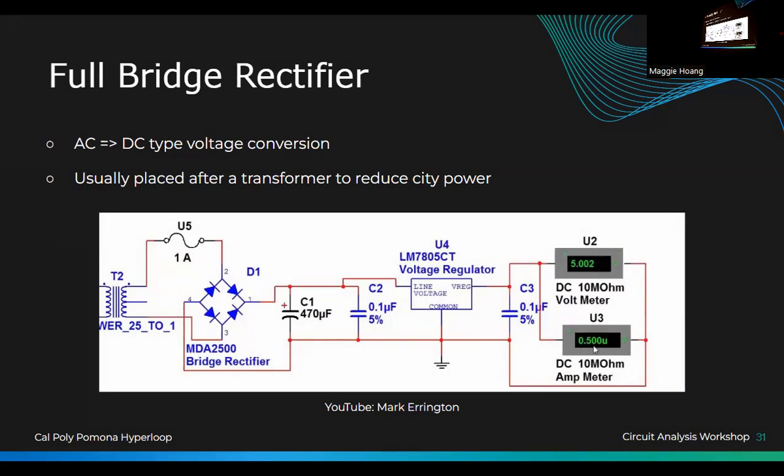And then after the diodes, it's gonna be like waves like that or something. And then with the capacitors, you're using it to filter it out. So after the capacitor, the way it discharges, it becomes like that. And if you have a straight enough line, you put it into the voltage regulator, and it can output a specific value.